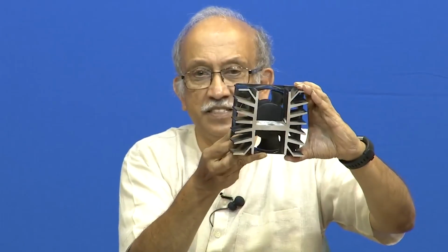If you go back to this fan, you see in the center portion there is not too much air flow. If you are an aero modeler, you must have heard of a spinner. In front of a propeller, usually you have a spinner. That spinner deflects the air, and here we do not need such things because of space. When you put these things together, you will see that these fins are directly in the air flow, and this area and this area have been reserved for components.